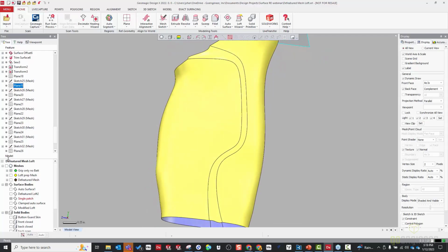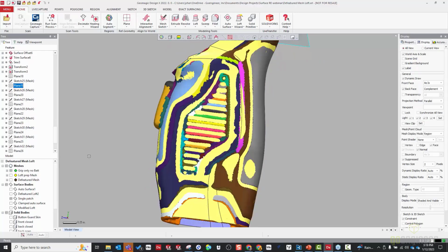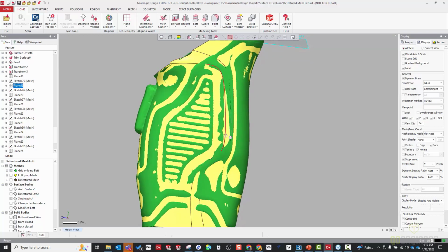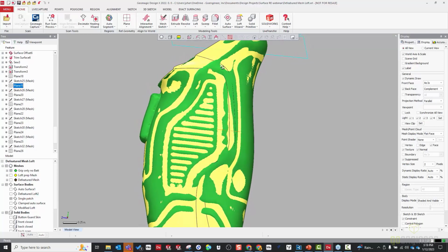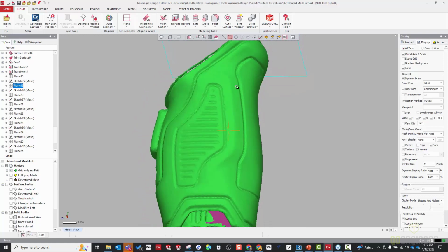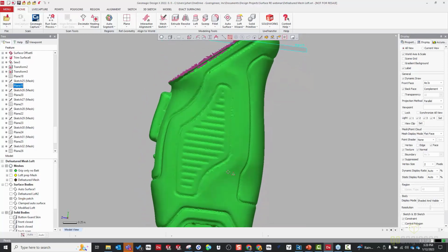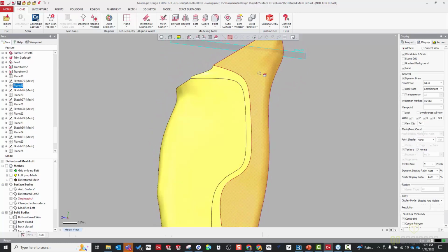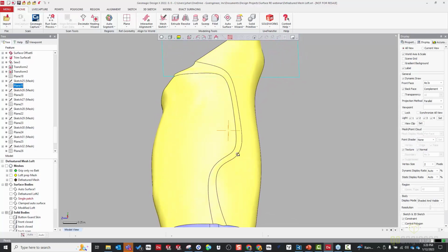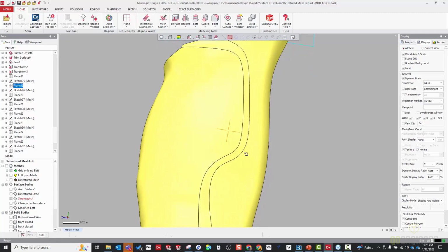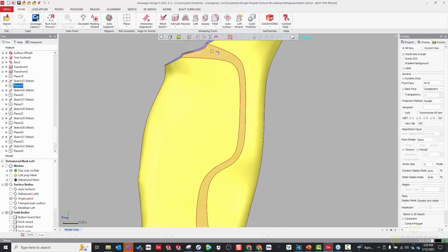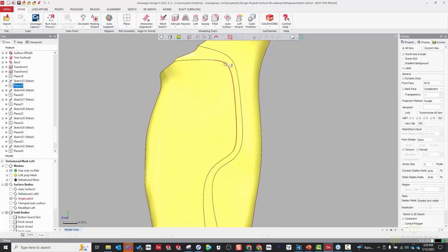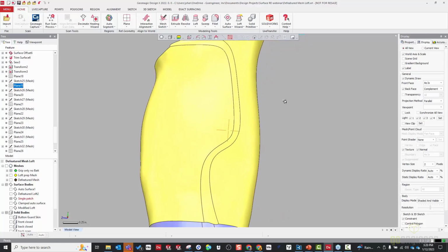And if I show the mesh, you can see that I tried to trim them along this line of curvature that's built into the handle. So I wanted to separate them there. And then you can also see that they're not quite touching. There's this bridging area. So one nice trick you can do is build in this gap between 2 trimmed surfaces and then use a loft operation to smoothly transition between them.